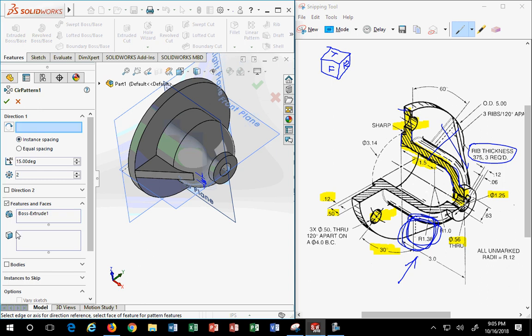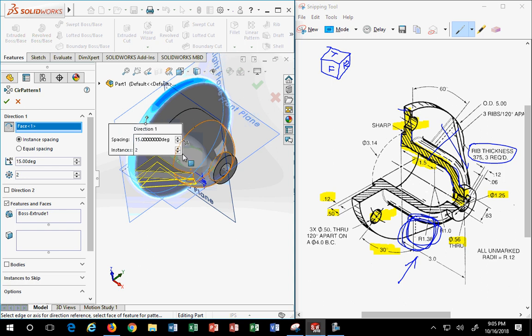No, the software is not intuitive. You have to intentionally know what you're picking. When you look to the left, there are all your options. Under direction, you have to actually identify the outer shape. You do want to identify how many you want, and I would recommend equally spaced. Or you can say instance spacing is 120. Of course, you could do that. That means the same thing as just saying equally spaced, because 360 divided by 3 is 120.